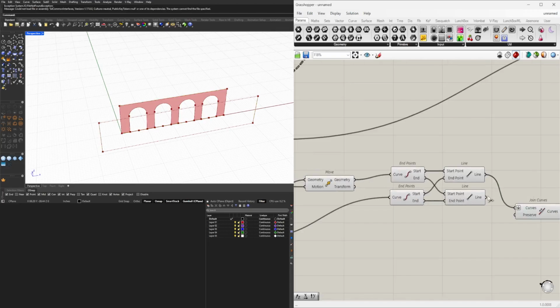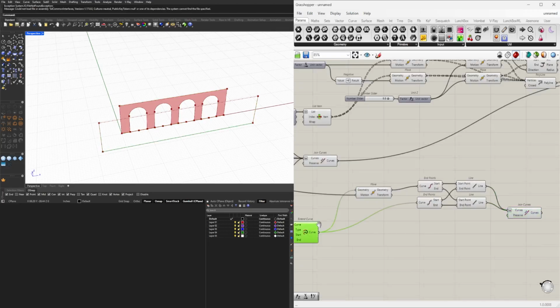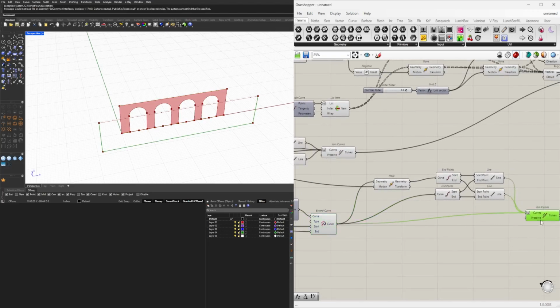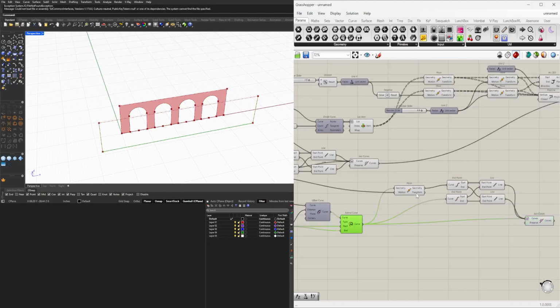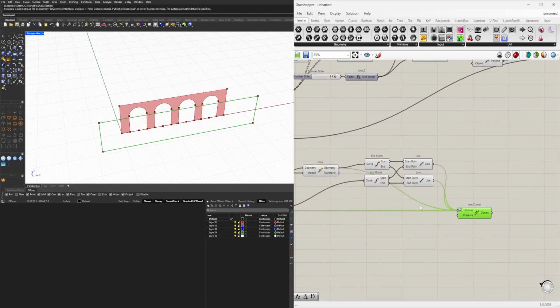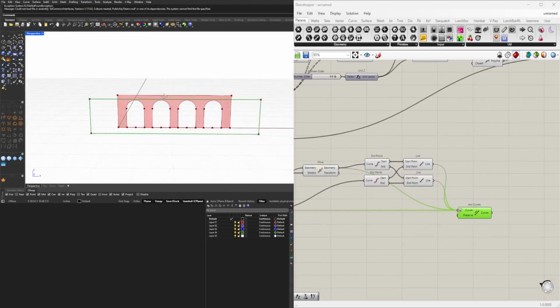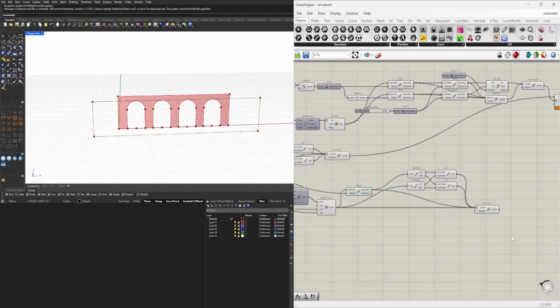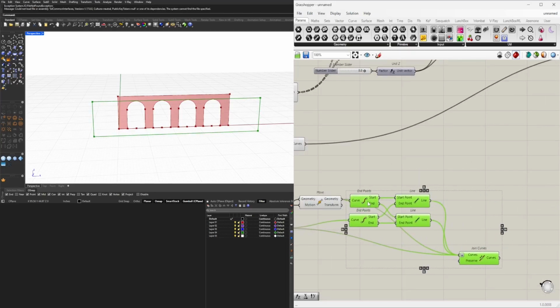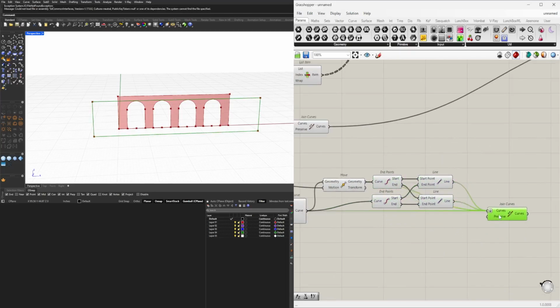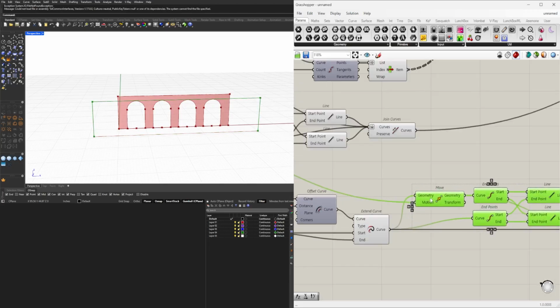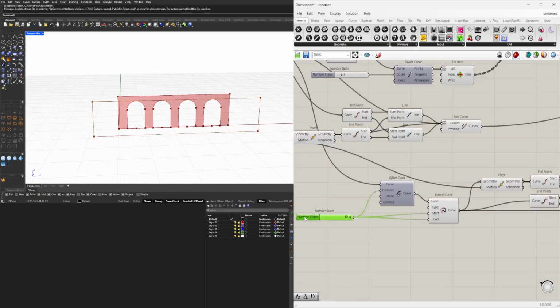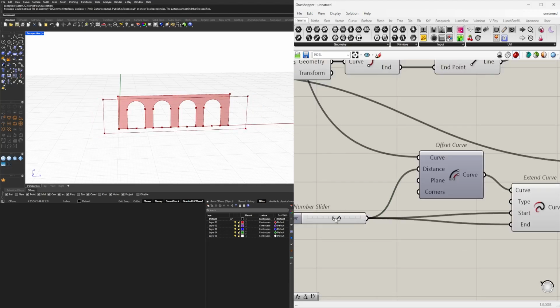And then we'll redo this because we need to plug in the new ones. So it's going to be this one and the top one. Holding down Shift, I'm adding all of the inputs to create this closed polyline. Now we could have done this again by ourselves, just moved it up, created the endpoints, and closed it into a closed polyline. So here we go.